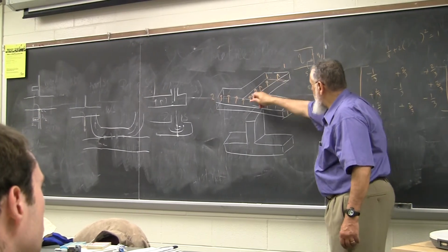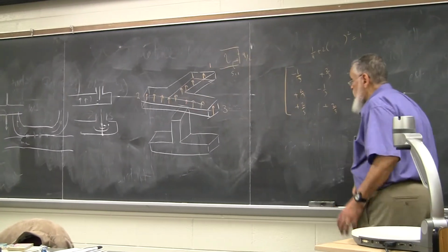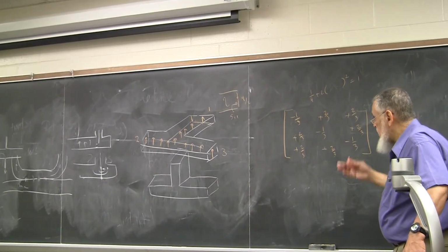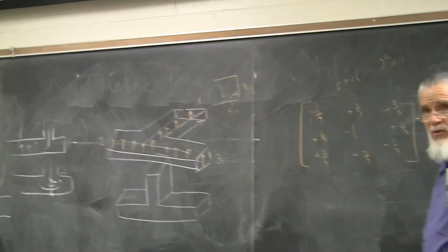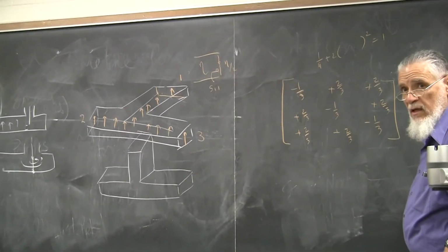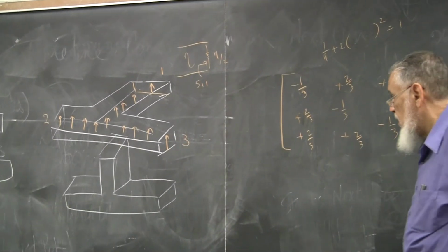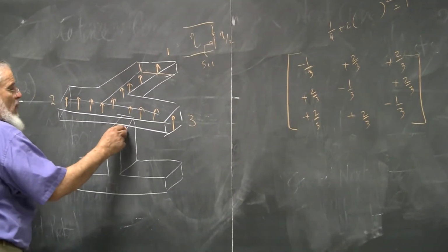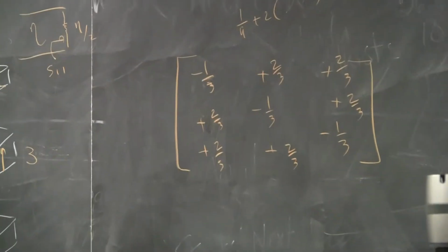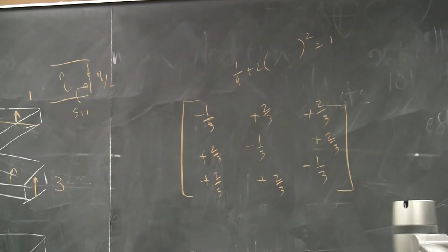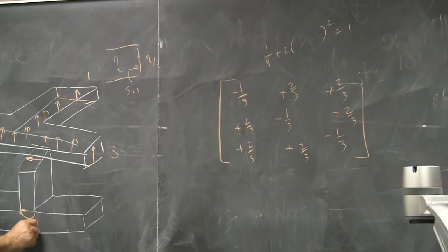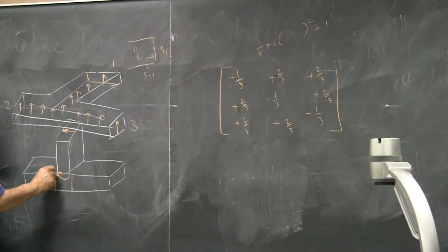It depends on how much is the delay in each arm of those. So you can get your S parameters that way, all right? You can obviously take the device to the laboratory and measure the S parameters and get them yourself. Now, the difference between this and that is if you put your field here, eventually it comes here, and that will fringe in there, causing one port to be positive and the other port to be negative.